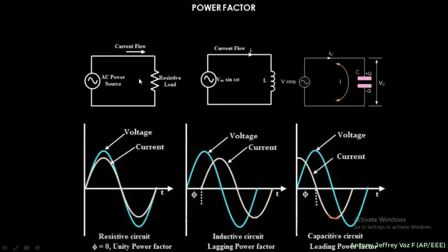At the same time, you see the currents which are flowing through them. Here is the current which is flowing through the resistive load, and this current is different from the inductive and capacitive currents. So similarly, all these currents are different. Here the inductive current is I, and here you can see the capacitive current is IC. So where is the power factor coming from? See the graph.